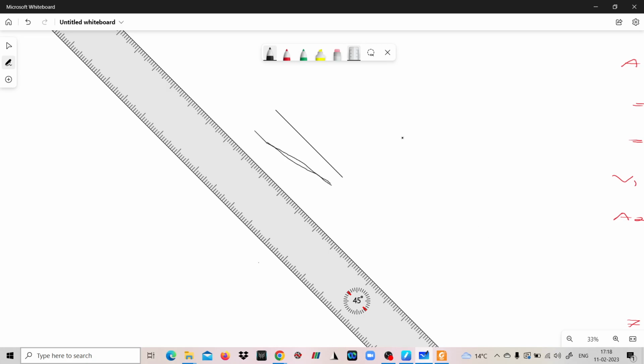Now for a tapering pipe, the slope is given. Say this is the pipe. If you consider the center line of the slope as the datum, then it will be easier for you. And then you simply need to apply Bernoulli's equation.